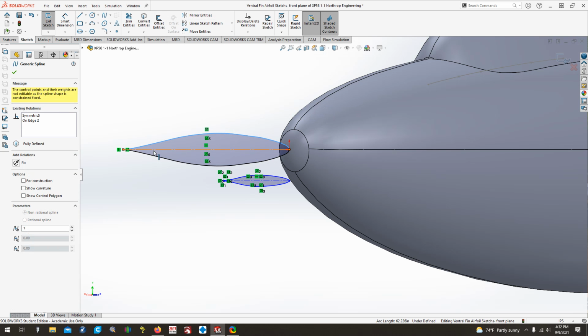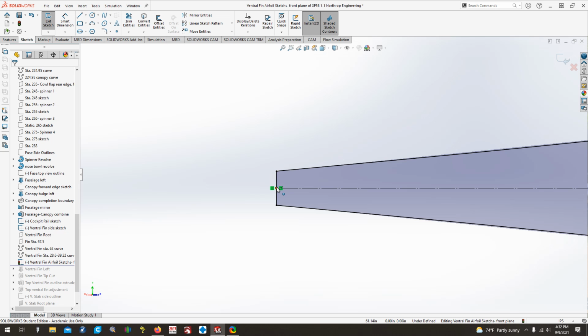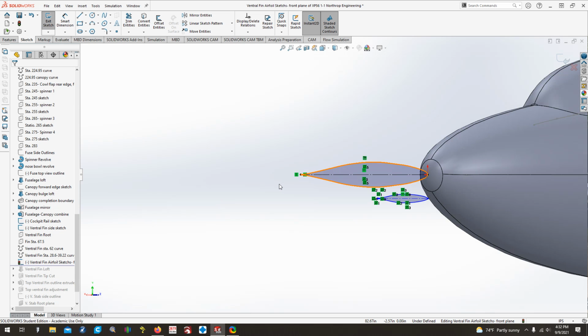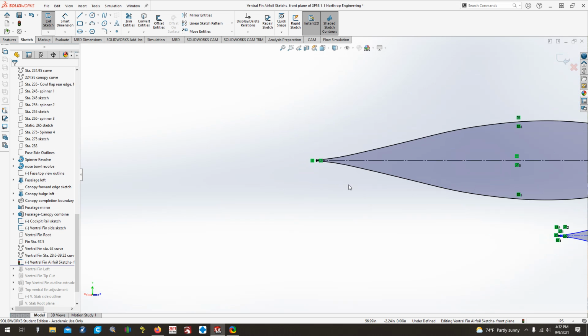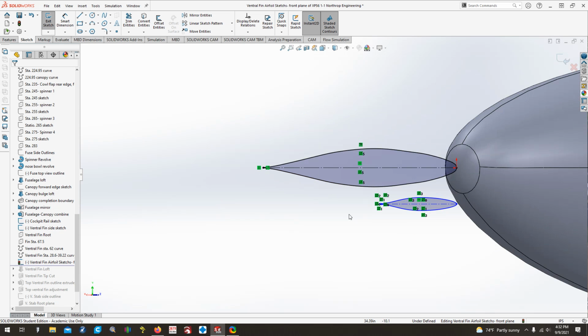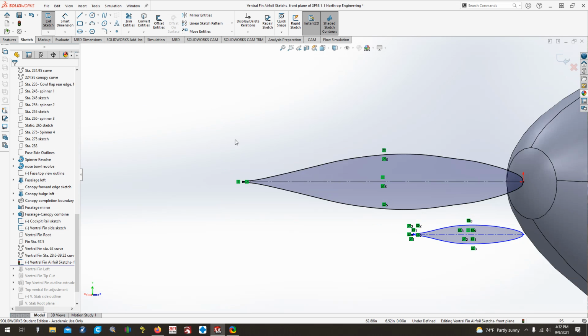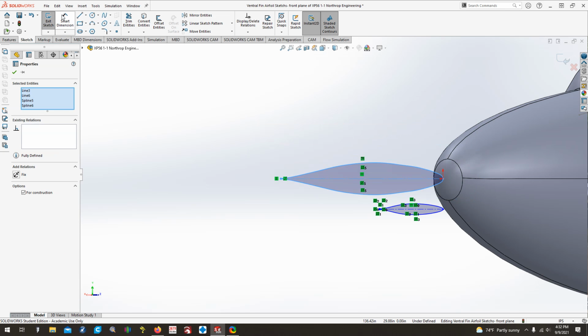I put a center line here. And then at the very trailing edge, you can see I just put a vertical line. Again, the documentation says it's a 50 thousandths radius. But since this is a CAD model and it's going to be scaled down, I did not do the radius. I just did a squared off trailing edge. So with those both created into a symmetrical airfoil, what you can then do is just click and drag across and then edit and then copy it.